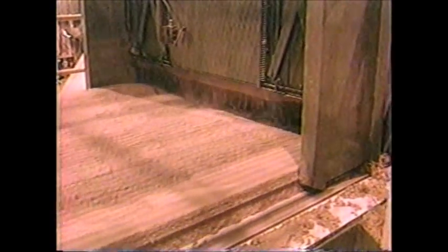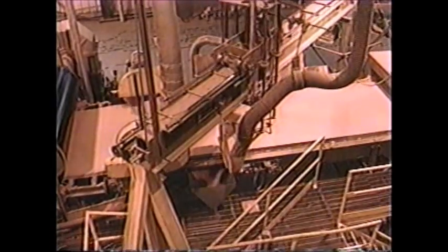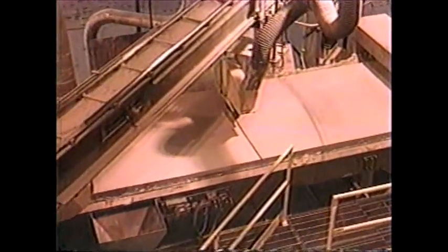The mat is laid down continuously in 3 separate layers, although the mat and final product is completely homogeneous in structure. The mat, about 4 inches thick, then passes through a pre-press, which compresses the mat to less than 1.5 inches. This makes handling the mat easier. The mat then is trimmed to slightly over 5 feet in width, and a flying saw cuts the continuous mat into length slightly over 24 feet.